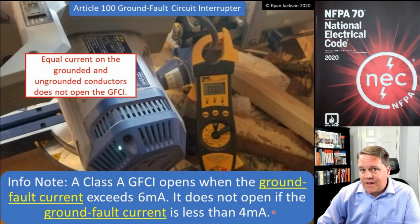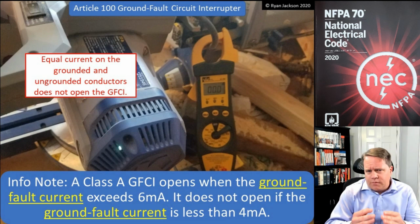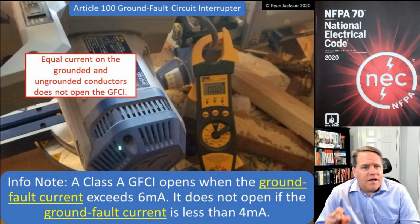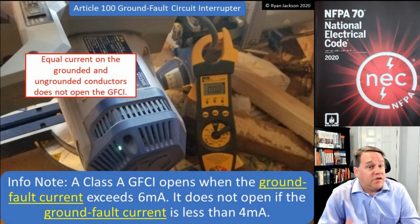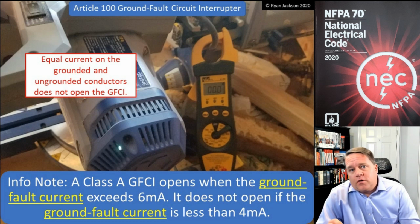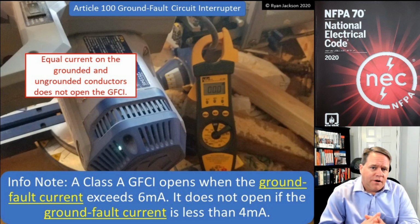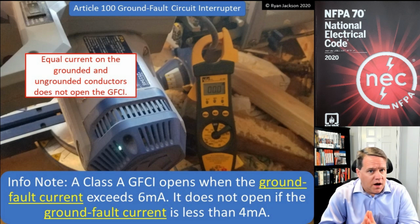So what is a Class A device? It's talked about in the informational note, and they cleaned up some language in the 2020 NEC as well. A Class A GFCI device opens when the ground fault current exceeds 6 milliamps, and it does not open if the ground fault current is less than 4. So somewhere between 4 and 6 milliamps of ground fault current or leakage current, that's where a GFCI opens.